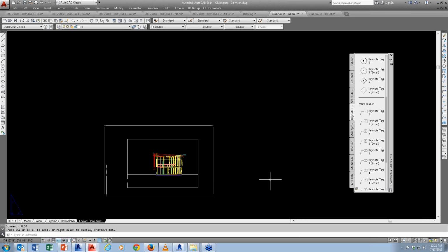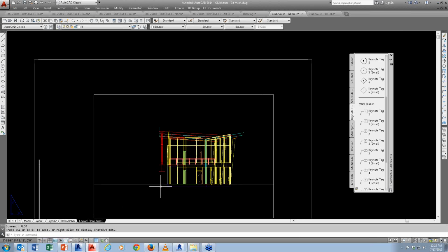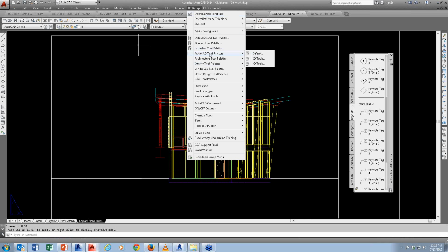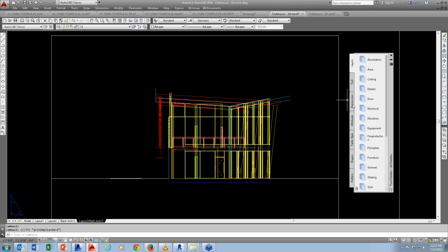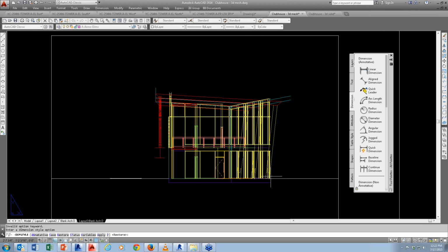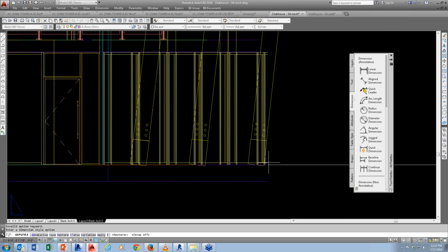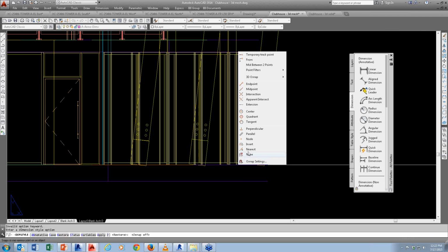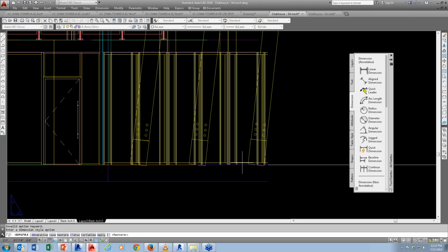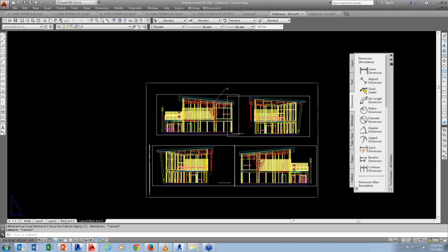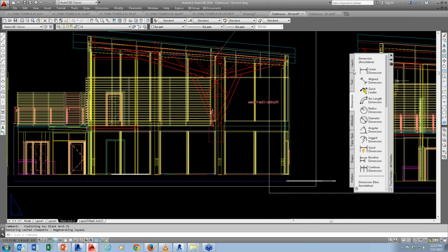You want to have dimensions in paper space? Yeah, the benefit of doing it in paper space, here, I'm just going to go in architectural, go to standard. You can actually dimension it. So for example, I'm just going to dimension my floor thickness. Let's see, go nearest. Yeah, sometimes it doesn't pick up. I'll probably have to go to the elevation. Let's see if it does this.